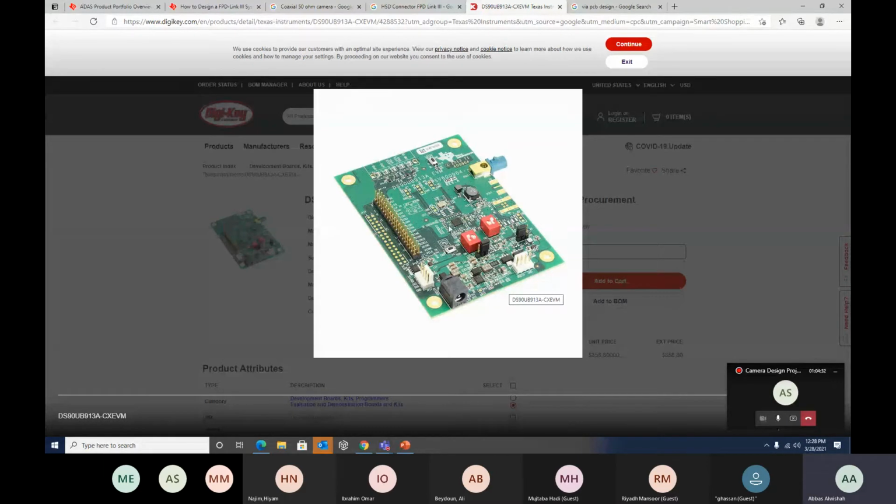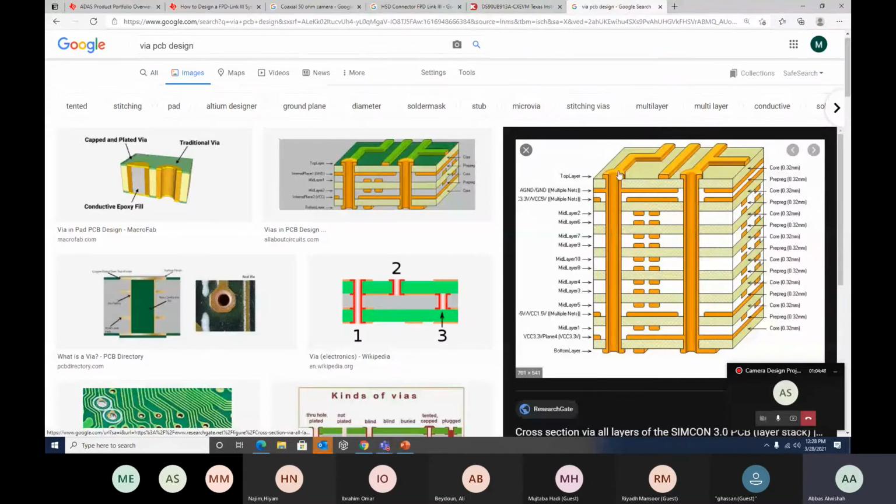You cannot really troubleshoot it, right? You need a couple of vias. You need a via here, and you need a via here to know that the signal that got in is right, the signal that got out here. And if it's right, then before you go to production, you eliminate the via.